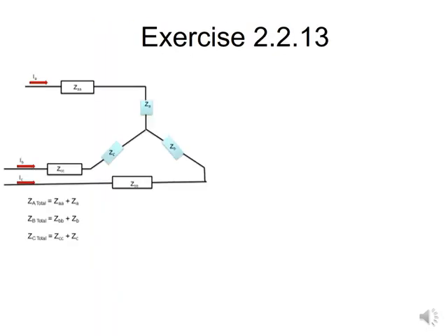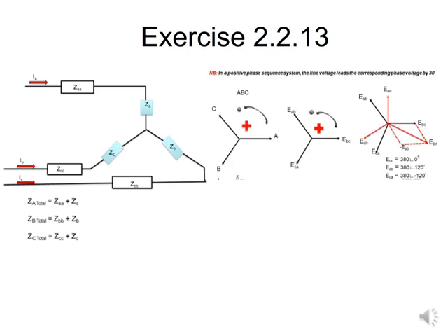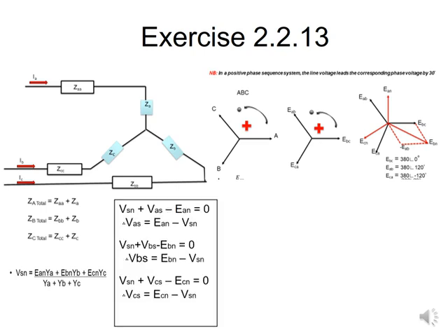Then we know that once we have it, we can now draw it as I've put in here, and I can say my ZA total becomes the one that was in series plus now what I've just worked out, and so is my ZB and my ZC. Once I have got those, then I go back to whatever voltage I've been given so that I can work out what my line voltages' relevant naming are going to be, and therefore my phase voltages. And I utilize those to work out my VAS, VBS, and VCS. Only then can I work out what my line current is.